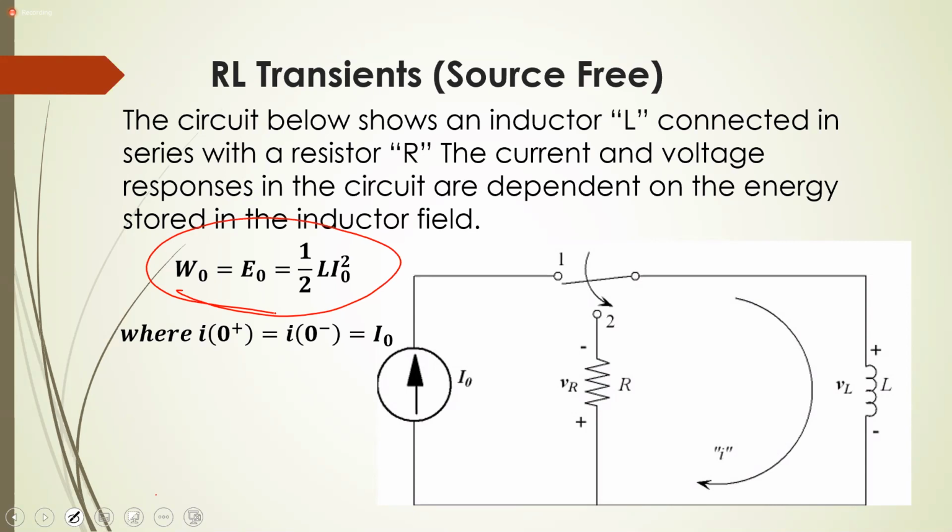Now, this statement that we have here, I don't think I use it for the capacitor with respect to the voltage, and I'll speak to that later. But for your inductor, this is an extremely important statement, something you need to pay keen attention to: I0 plus is equal to I0 minus is equal to I0.